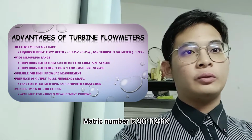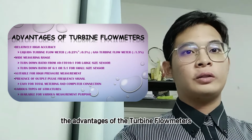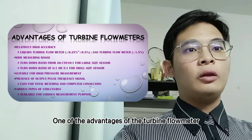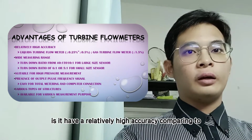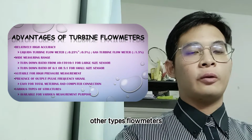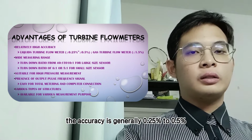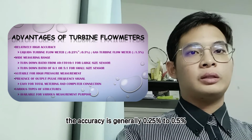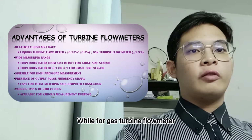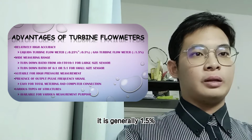I am going to talk about the advantages of the turbine flow meter. One of the advantages of the turbine flow meter is that it has a relatively high accuracy compared to other types of flow meters. For liquid turbine flow meters, the accuracy is generally plus or minus 0.25% to plus or minus 0.5%, while for gas turbine flow meters, it is generally plus or minus 1.5%.